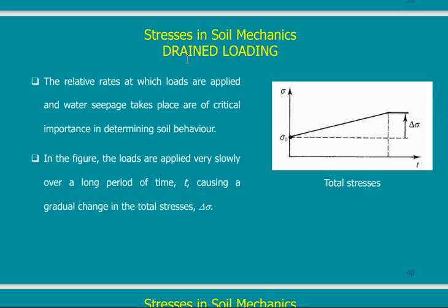But if I am simulating the clay, then especially at the beginning, when I want to simulate the onset of the test, I should have it undrained. Why? Because water will be trapped. Water will not be able to leave.